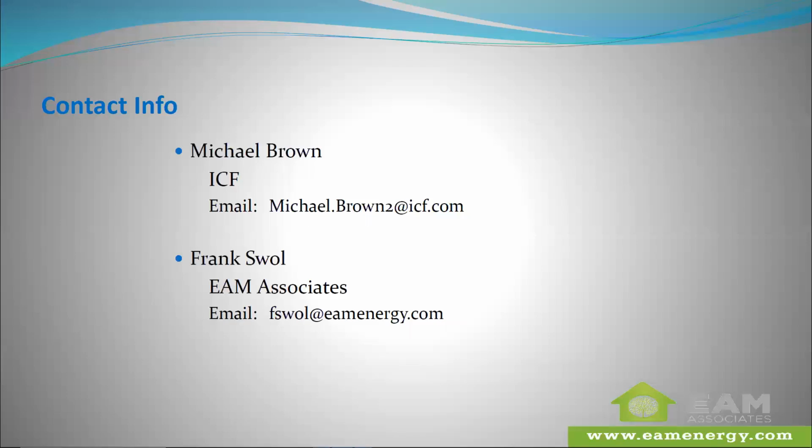And then Energy Star, for example, has guidance. Manual J has defaults like tight, semi-tight, and average, and Energy Star has some guidance on what you should use for an Energy Star home at least. So if you're building to infiltration rates similar to what Energy Star specs, you could look at those and give that guidance to your designer as well.